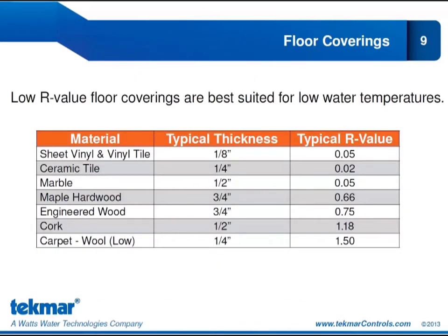When we're designing low water temperature radiant installations, it's very important for us to consider the R value of the floor coverings. We want to design with the lowest possible R value that we can. So this is a list of typical thicknesses for a variety of different floor coverings and what their typical R value is. You can find information like this at a number of sources.